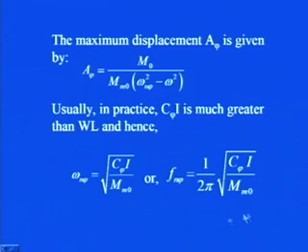So, in this class we saw how we can get the measure of damping using the damping factor in the case of free vibration tests and forced vibration tests. After that we saw how we can go for the analysis of block foundations, and in that we saw that there are basically 6 degrees of freedom, that is, translation and rotation about the 3 coordinate axes x, y and z.